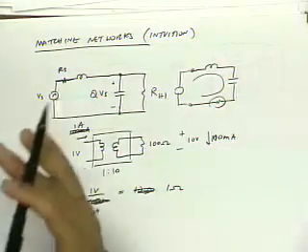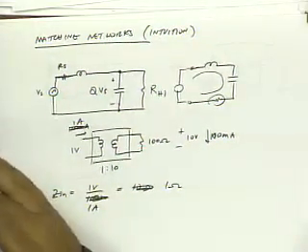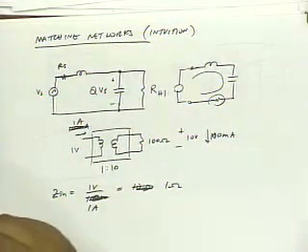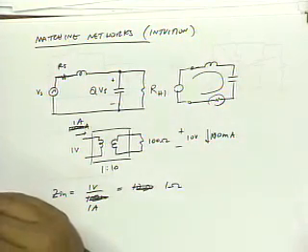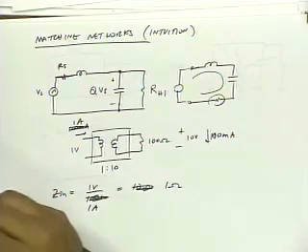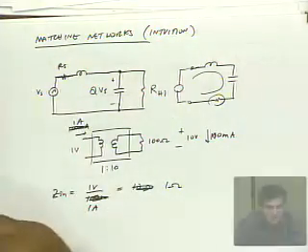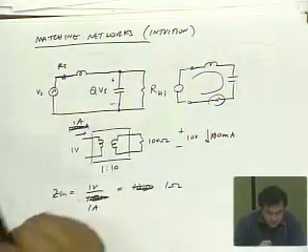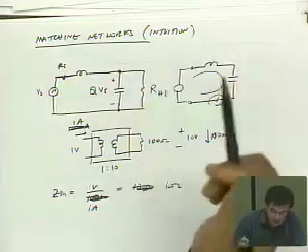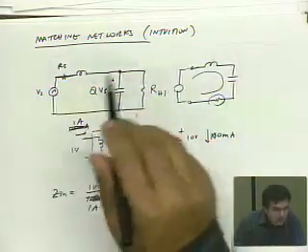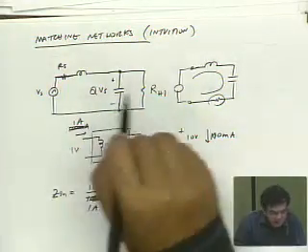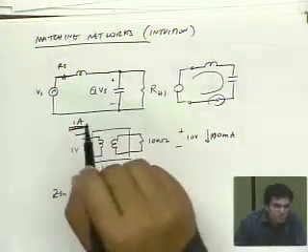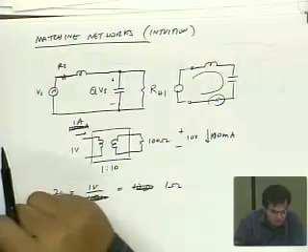So if you didn't do any calculations and you said, I have a circuit that can boost the voltage by a factor of Q, therefore it should be able to boost the impedance by Q squared, or vice versa. That's pretty much what we found when we did the exact analysis. The only difference was it was 1 plus Q squared. And the reason is that we don't exactly have series and parallel circuits. They're slightly different. When you transform them, that extra factor of 1 comes into play.